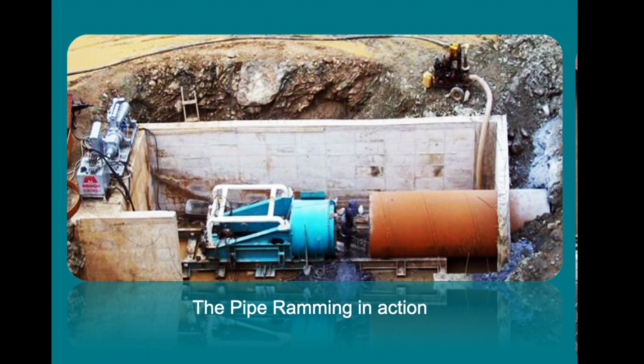The pipe ramming method is quite simple. A steel case is pushed by hydraulic jacks, usually two hydraulic jacks, each of 100 to 200 tons of pushing power. The progress of moving is 1.2 to 1.3 meters, and the jacks and the attached pipe are placed into the working ditch. It must have the necessary depth with straightened walls, which can withstand pressure during implementation of works. A hydraulic drive which activates the jacks is placed on the surface near the ditch.